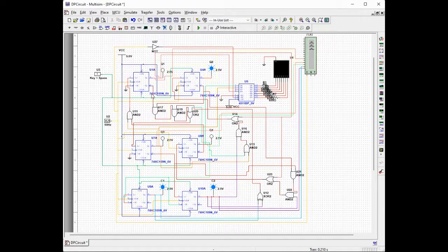So now I'm going to be running through my student number in my Multisim simulation. You can see I have my reset wiring up here in green to this digital interactive constant. So when I click space, that will activate those presets and clears. I'm going to press play, and we should see we're at my starting number, which is 4. Then I will press space again, and we'll see it run through this. 4, 0, 0, 3, 0, 2, 8, 5, 3. And there we go.